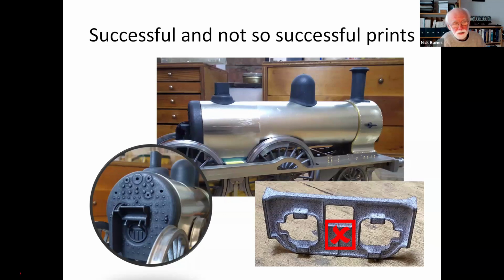There's individual springs on each of those wheels, and the horn blocks would deform under the action of the spring. And I didn't actually have one break, but I could see that they were going to break before very long.